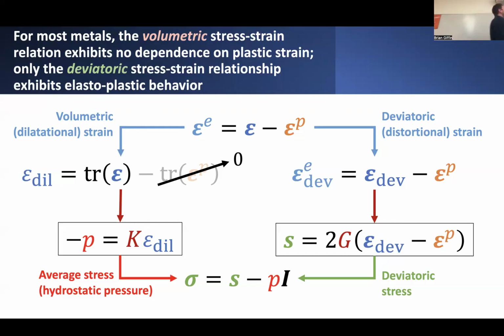So in effect, we shift the deviatoric strain in the material by the corresponding plastic strain, which is itself by definition a purely deviatoric tensor. It has a trace that's equal to zero. We find that we can describe this deviatoric stress tensor S just purely through this simple relationship that depends on G, the shear modulus. So quite simple, quite nice.